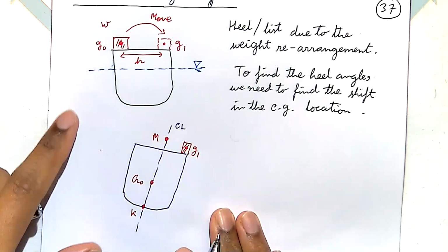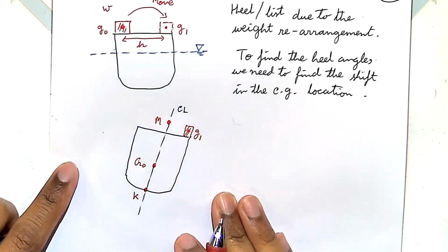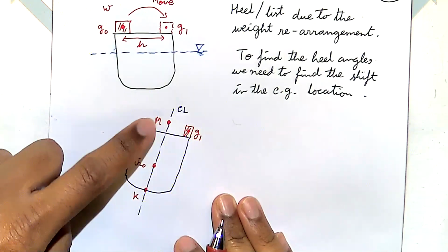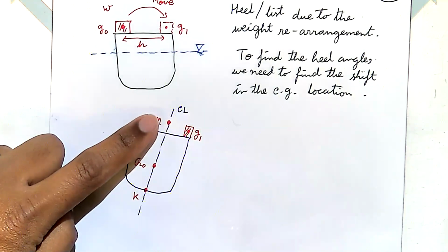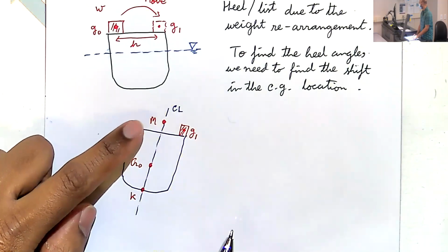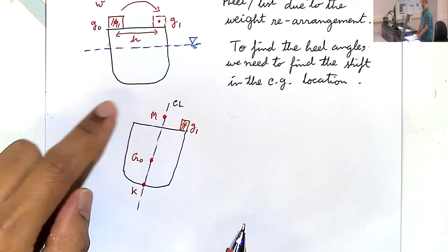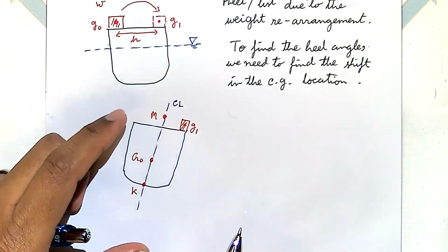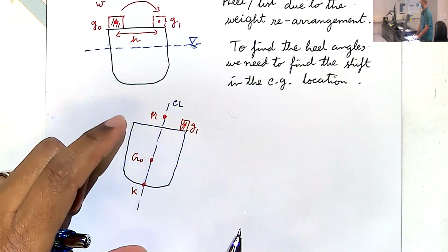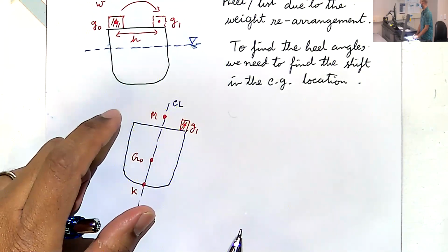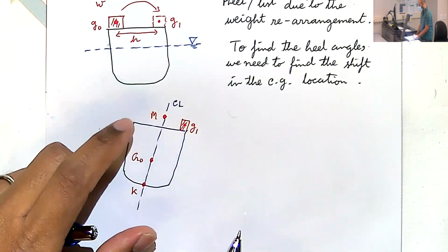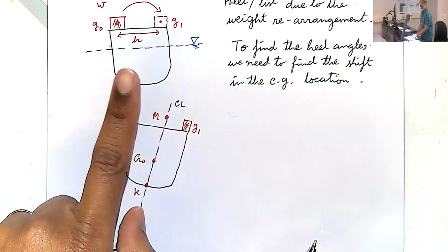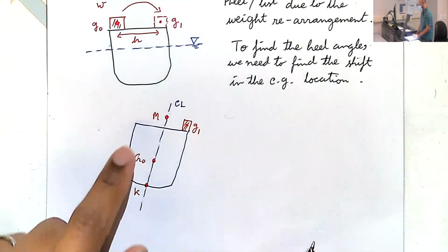Hold on, what do you mean by small angle changes on the metacenter? I thought it was always fixed and based on the shape of the hull. No, if you look back to how we computed the metacenter, it depends on the submersion. Oh, that's right. So as you tilt, the whole shape changes. Yeah, exactly. So for small angles, we can assume that the change is not huge, so the metacenter stays fixed. That's right. If the heel angle is more than 10 degrees, then we cannot use this assumption anymore.